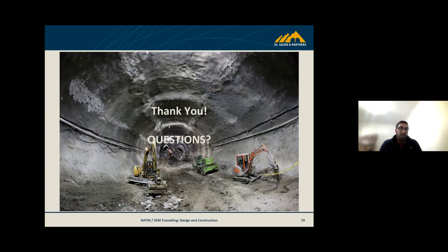Stand-up time wise, it's very dependent on water content and what exactly the ground is in that location, and with the variability that you get, there are locations, I think, where the stand-up time could be better because of the clay content, but I don't think it's going to be anywhere near as good as the nice London clay that we see for all of these large infrastructure projects in central London.